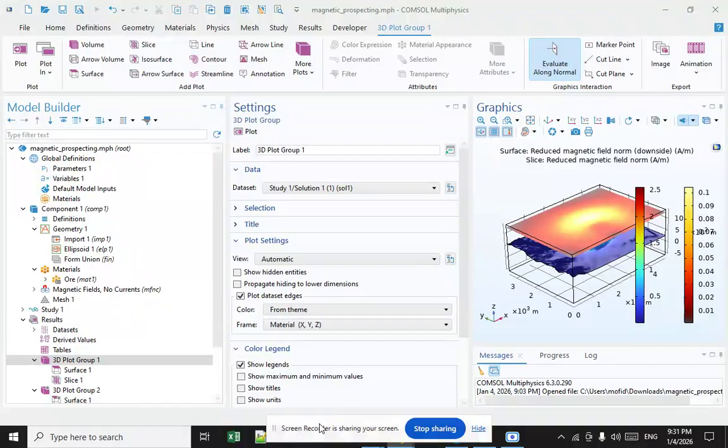Magnetometry is therefore useful for finding pits and ditches which have been backfilled with topsoils with a higher magnetic susceptibility than the surroundings. Roads and structures are also visible from the magnetic survey since they can be detected because the susceptibility of the subsoil material used in their construction is lower than the surrounding topsoil.